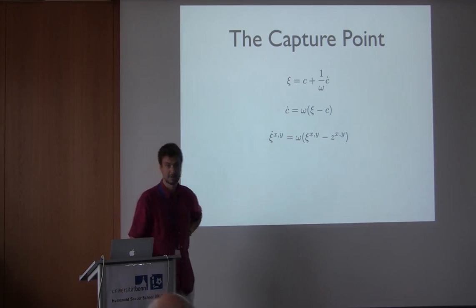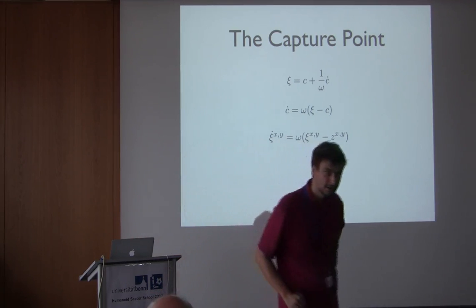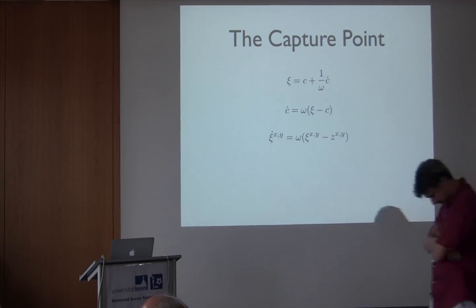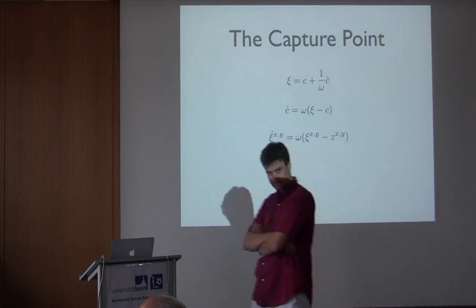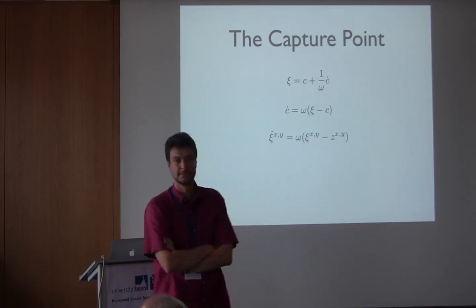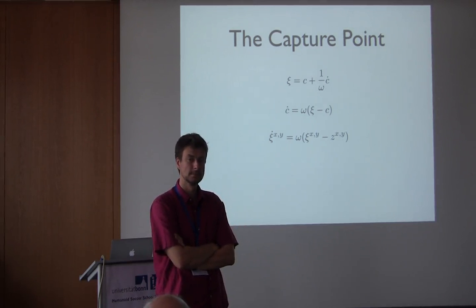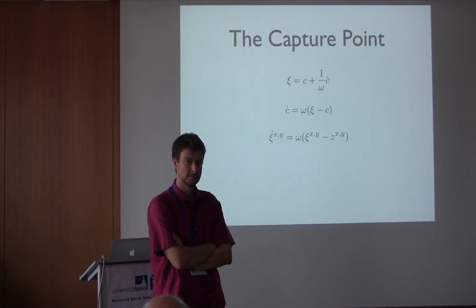When I look at this passive walker that Jackie brought, or there are also versions that walk on level ground with some powering, but they are mostly governed by the natural dynamics. So not only of this inverted pendulum of the center of mass, but also by the hanging pendulum of the swing leg. And to me, this looks much more natural in some way than maybe the HRP4 walking.